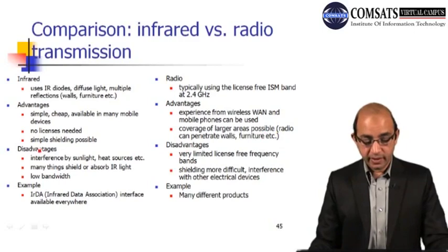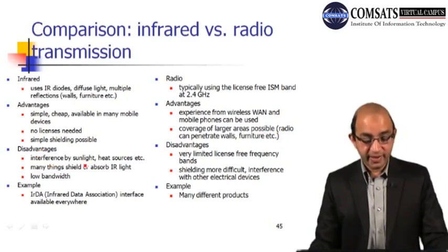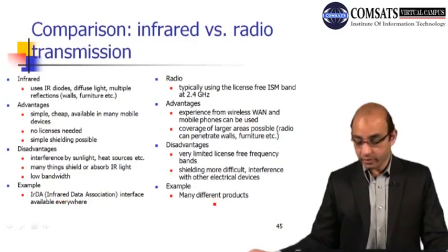And here are the disadvantages for IR: interference by sunlight and heat sources, and a very limited license-free frequency band. This again goes to the cost disadvantage over there, low bandwidth if we talk about the infrared, right? And one example is Infrared Data Association, with many different products.